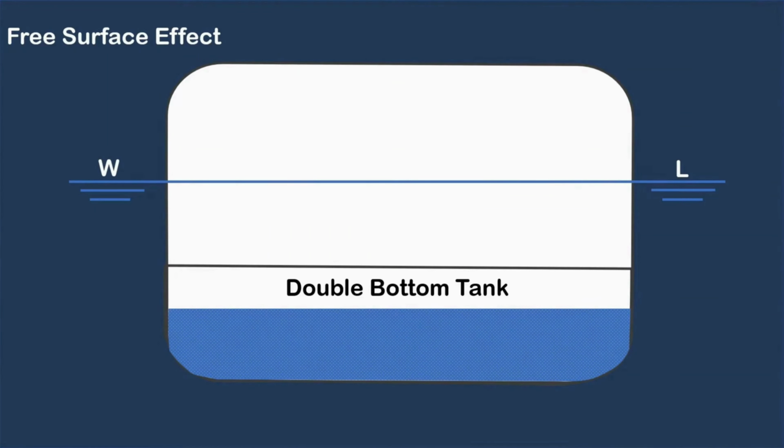The geometrical center of underwater volume is the center of buoyancy, marked with capital letter B, where the buoyancy force acts vertically upward. For a ship to float, the buoyancy force should be equal to the total weight that acts vertically downward. When a ship tilts or rolls, the ship's center of buoyancy, capital B, moves to some point at the low side, to be B1.